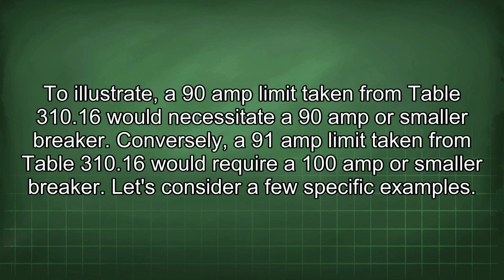To illustrate, a 90 amp limit taken from Table 310.16 would necessitate a 90 amp or smaller breaker. Conversely, a 91 amp limit taken from Table 310.16 would require a 100 amp or smaller breaker. Let's consider a few specific examples.